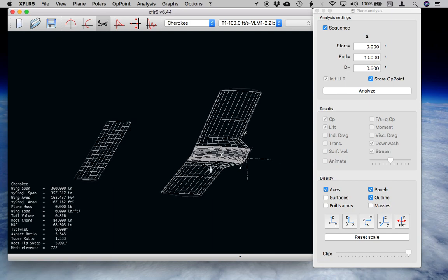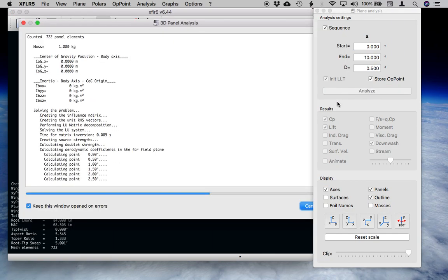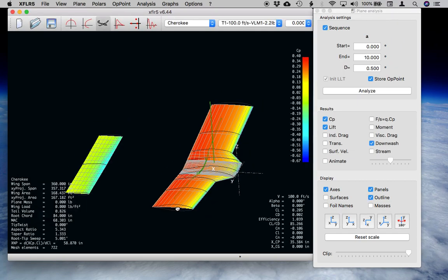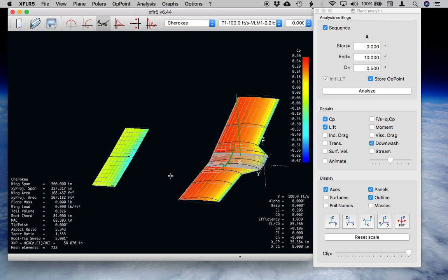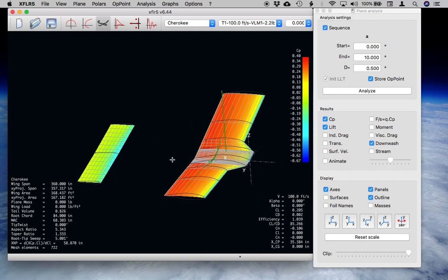Again, this is just used as an example, and then we could run through and do a full analysis of this. And so it not only gives us the pressure coefficient on our main wing, but also on our horizontal tail plane. We could throw in a vertical stabilizer in there as well, and then also start to define a fuselage, but we'll come back and do that later.